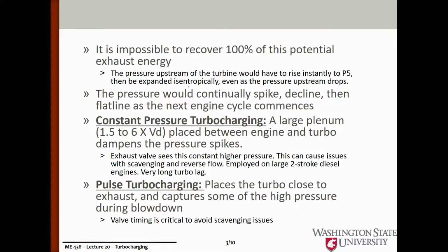And then you need a perfect isentropic expander that was perfectly isentropic at a huge range of flow rates and pressure ratios, something we cannot design a rotor to do. If you were to do this, the pressure would spike every time the valve opens, then steadily decline, and then be flat after the exhaust stroke, and it would remain flat until the next cylinder opened up.